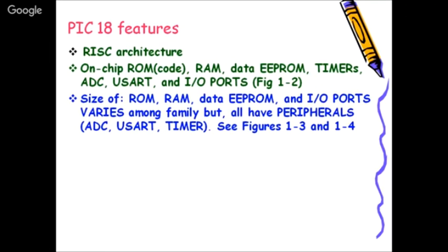And then on-chip ROM. There is an on-chip ROM, that is, code memory, and that can go as high as 2 megabytes. I was telling that the program counter of the PIC controller is 21 bits wide, that is, 2 to the power 21. 2 to the power 20 is 1 megabyte. The program counter is one indicator of how much address space it can access. If your program counter is 2 to the power 21 wide, that means it can go up to 2 megabytes, with 8 bits for each address location.